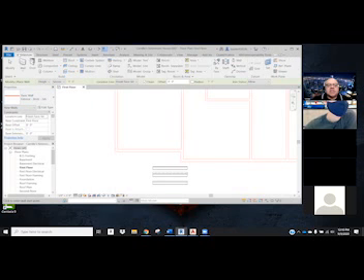So go Architecture and Wall, and you'll find that there's Modify and Place a Wall. Then we have height, and right now our height is locked to go from the first floor to the second floor. Okay, now that's only 9 feet. We can adjust that height later when we talk about the elevations of the building. But right now that gives you an 8-foot ceiling, which is a standard residential ceiling height. It's kind of becoming a little bit less standard, but that's okay.